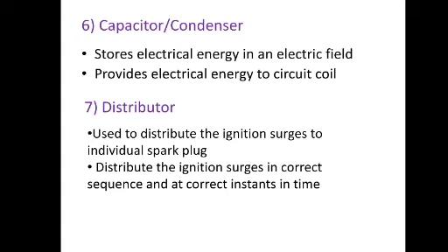The distributor unit consists of several other auxiliary units. In the lower part of the housing, there is a speed sensitive device or governor. The function of this is to advance the spark with an increase in engine speed.